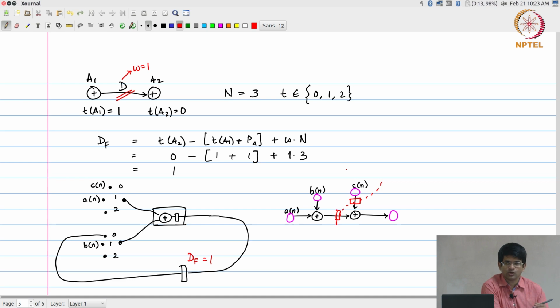When I draw the data flow graph, that detail gets hidden away because I am not treating my sources as separate nodes. So, in other words, when you are actually implementing these things, you need to apply your mind and make sure that you are doing it correctly. The pipelining step that you use is valid and that you have delayed all the inputs appropriately so that you get the correct output. As long as you take care of that, the approach itself will work.